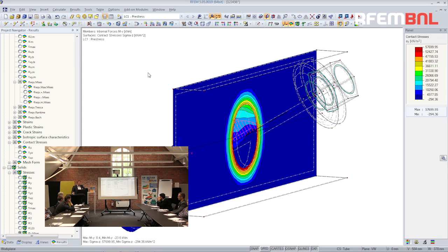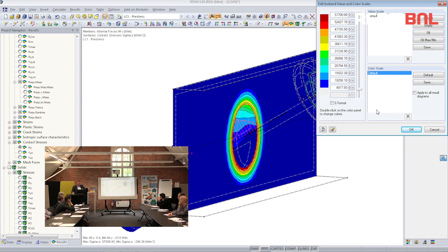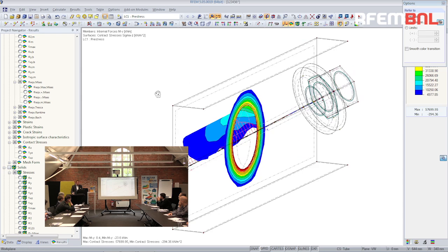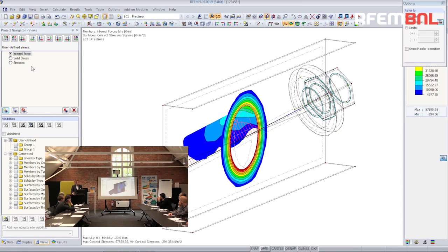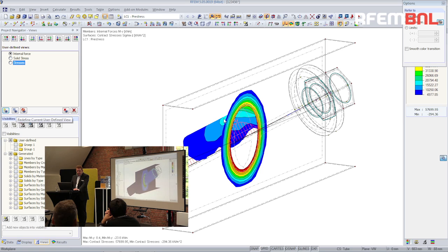You go to calculation parameters, and here are the nonlinearities, and automatically you see that we use surface and elastic foundation supports nonlinear. It's always good to check. So this was adapted. So take a look at the views, the results, for instance, for the surface, and there in the surface there's now the contact stress. There is sigma z, like that.